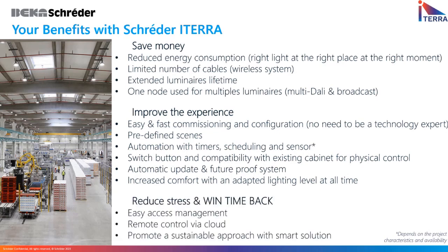Another benefit is that you will then use one node for multiple luminaires. So if we use the function of multi-DALI or broadcasting, then certainly we can connect multiple luminaires to one device. There are limitations to how many devices can be run, and that's all in our data sheet. So if someone wants to understand that, I can explain that to you.